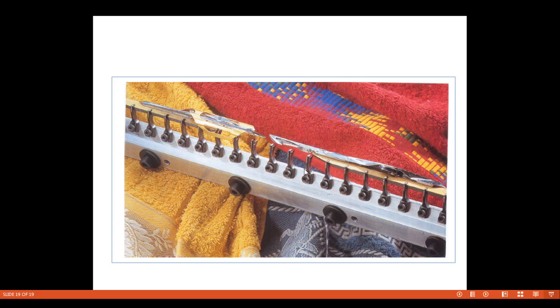So we have seen there is a disadvantage in the guided rapier. We cannot have more EPI. If more EPI is there, during opening and closing the warp abrades on these teeth and chances of warp breakages are there. And the same, a fabric with more EPI we cannot run, and also more fancy yarn in the warp we cannot run, due to the increase in breakages.